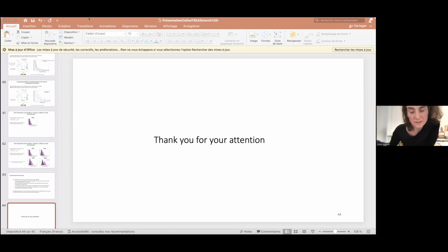No, the hazard is already high. The hazard just with the area model, area enclosing the fault system, is already high. So it's even higher, that's true. It's like 0.3 g at 475 years return period, or 0.4, which is already high.